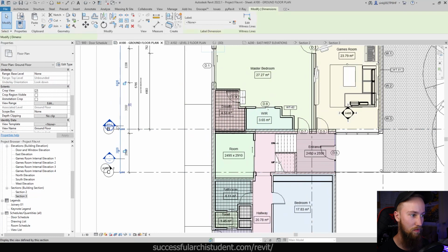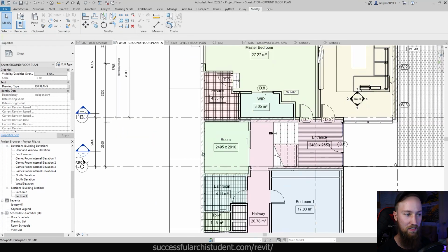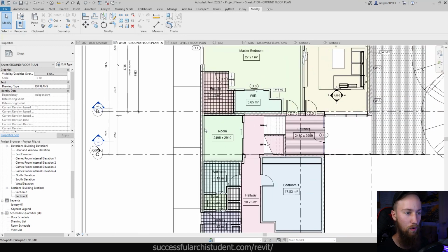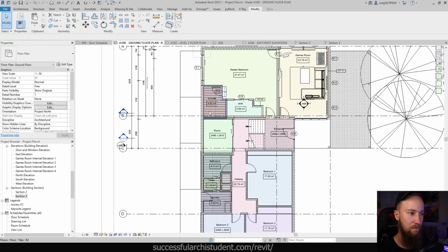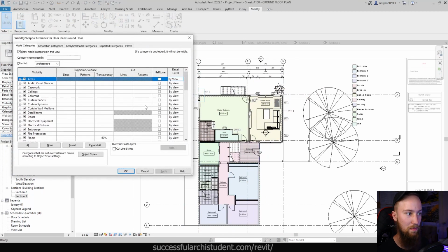We might have to move this out a bit. So considering we haven't really defined what these brick walls actually are, and we haven't gone out on the site and measured that they are in fact a 50mm cavity with a 110mm bricks or whatever it may be, we don't really want to show the exact configuration of that wall. So instead, what I'm going to actually do is change all of these walls in this view to have a black cut fill.